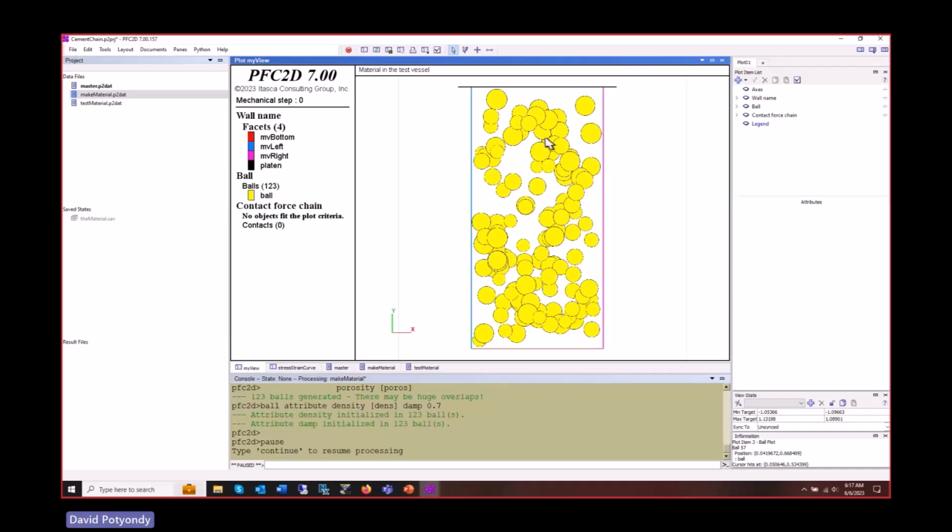To make a specimen, if you want it to be actually the most realistic, you would take particles and just let them fall under gravity and build this thing up and then bond them together. That's going to be a relatively slow computational process, whereas if you do this and make them push apart, you can achieve the packed state much quicker.